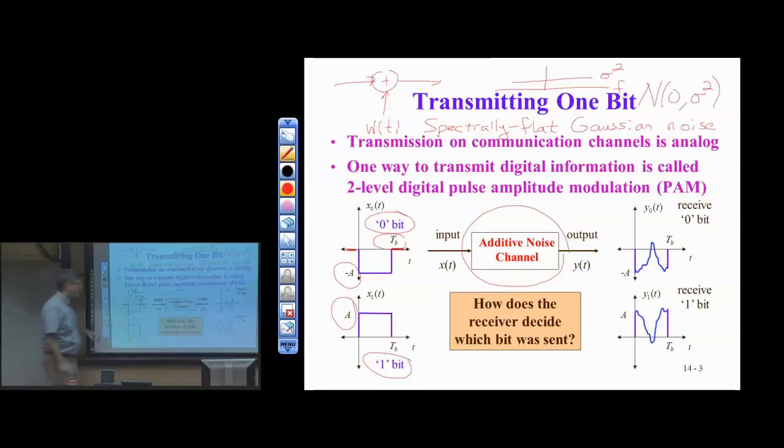All right, but for now, I'm only modeling the additive noise in the channel, nothing else. We'll have a filter here for frequency-dependent distortion. The receiver is going to receive the transmitted waveform plus, at any point in time, the additive noise. That means for any point in time, I'm going to add a random number to the transmitted waveform. That's all I'm doing here. It's a simple channel model. I've given you a hand drawing of what that might look like here on the right. This isn't an actual simulation, just a hand sketch. So I might see something that looks like this over the bit duration.